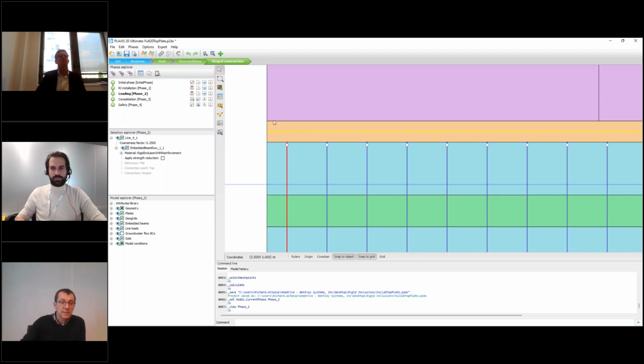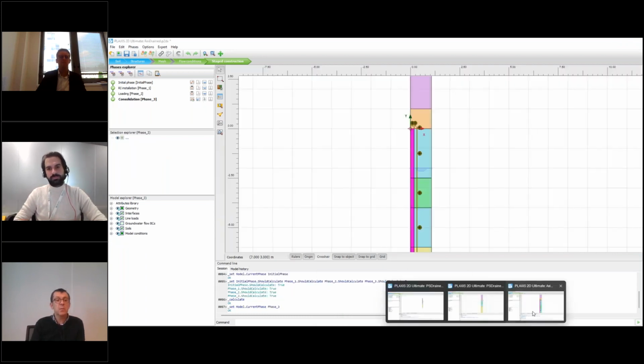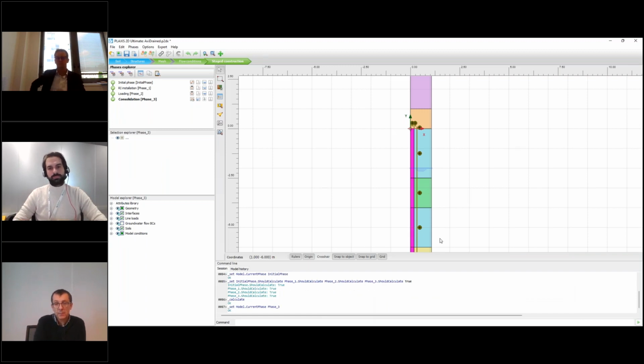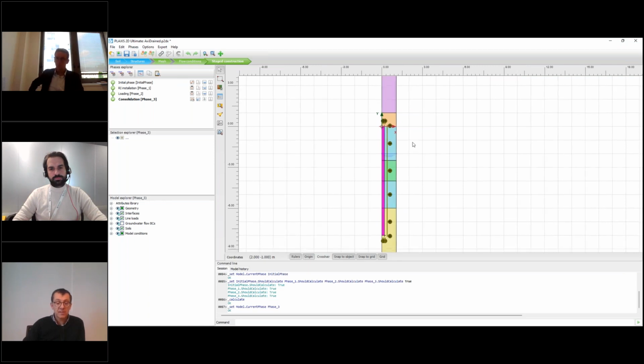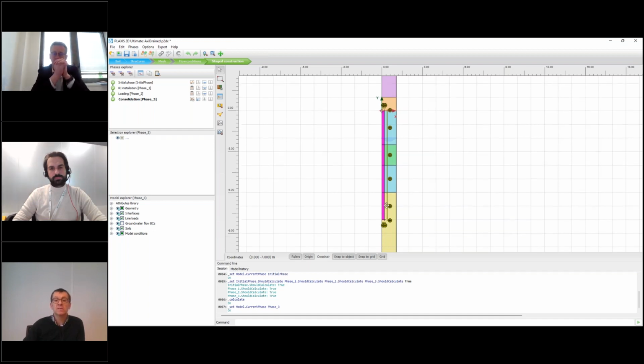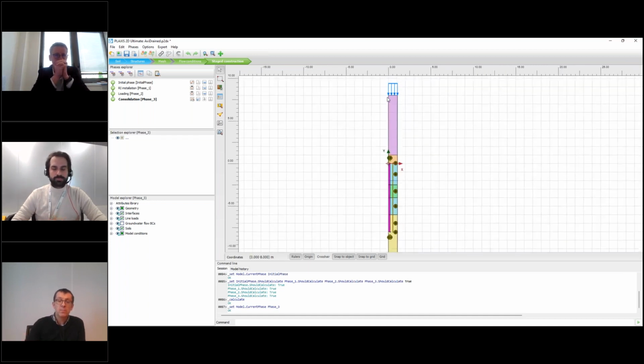So that's the strategy that Jérôme has presented, which consists first in setting up an axisymmetric model. This is the very first model one will be doing. It corresponds to a single cell, which is represented in an axisymmetric way, where the rigid inclusion is introduced also here using volume elements, or soil elements. And the characteristic here is the way the model width, the radius of that model, is introduced.